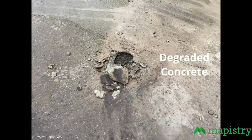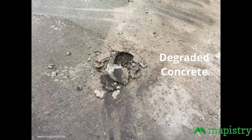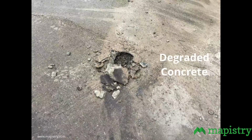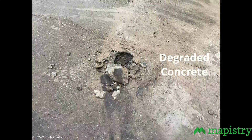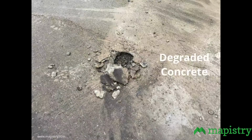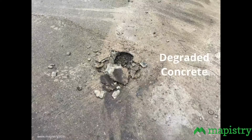Same thing if you have a site that's degraded. If you have degraded concrete that's spalling, cracking, chipping up, especially near storm drains, I was talking about earlier, vacuuming around storm drains. If you have worn pavement, worn concrete, these can be contributing small particles. Not only do you have to be doing really good housekeeping from a sweeping perspective, but you have to be doing really good preventative maintenance on your physical infrastructure, making sure that you're not contributing sediment from the breakdown of your infrastructure, even though you're on a paved surface.